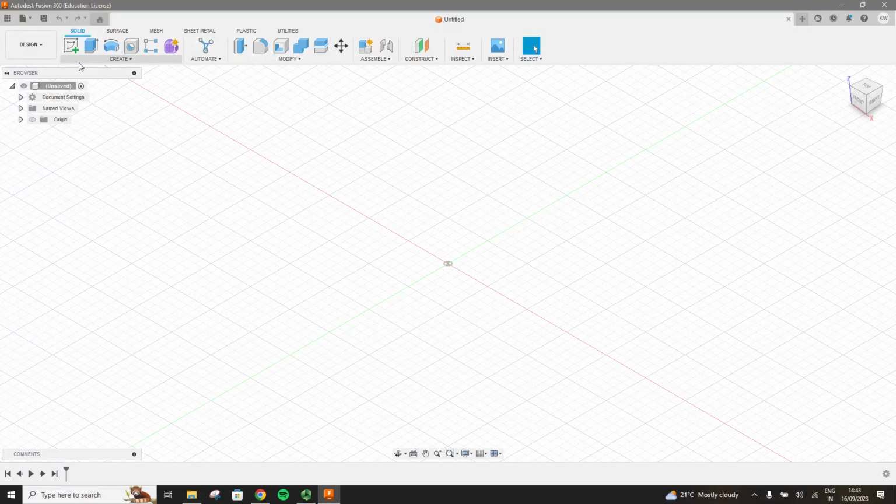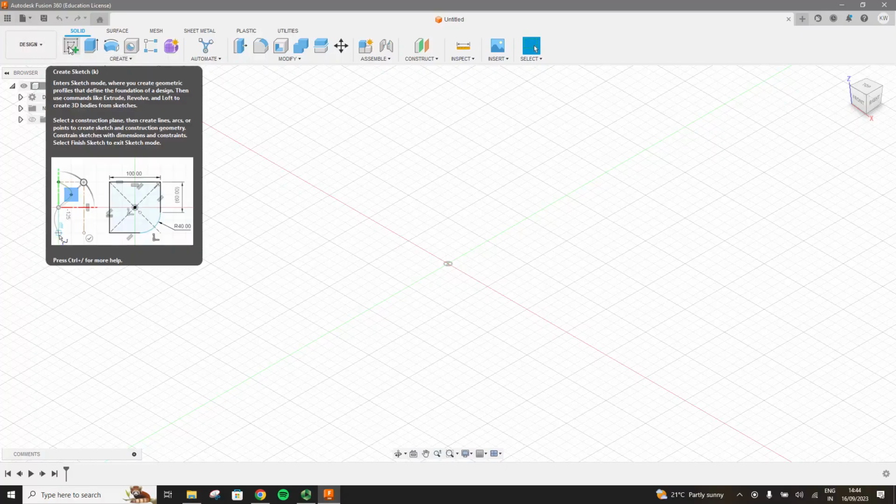So you can make a sketch, and today we can see 3D sketches as well, by the way. So you can make a sketch and you can have a profile, and that profile can actually follow the sketch, making something like a tube. For example, if you want to make a pipe which is bending at different angles, you don't essentially want to make a lot of cylinders and a lot of fillets. What you would want to do is make a path for that pipe, maybe make a profile of that pipe or tubing, and then have it just sweep along it. So let's go ahead and do some of these exercises for sweep and see how it works.